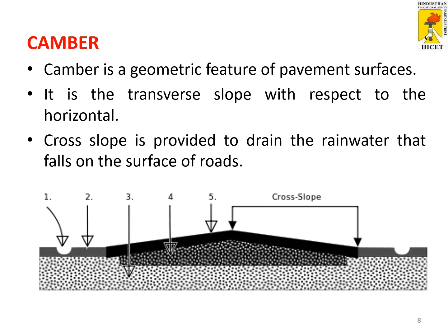Number 1 indicates the ditches. Ditches collect the rainwater and dispose of it safely. Number 2 is the wearing surface, third is the subbase, fourth is the base, and 5 is again the wearing surface. So the slope is given from the base layer and the wearing surface.